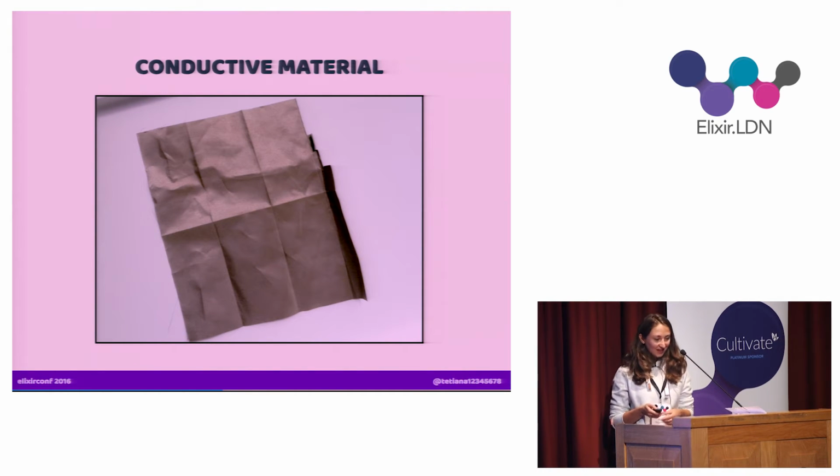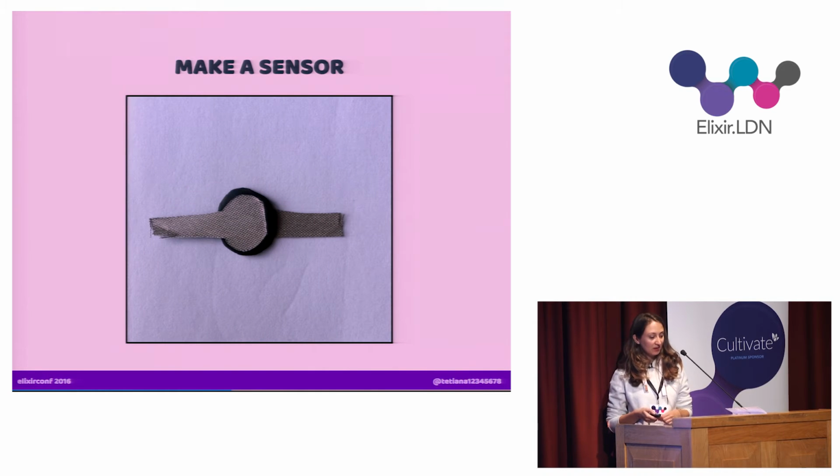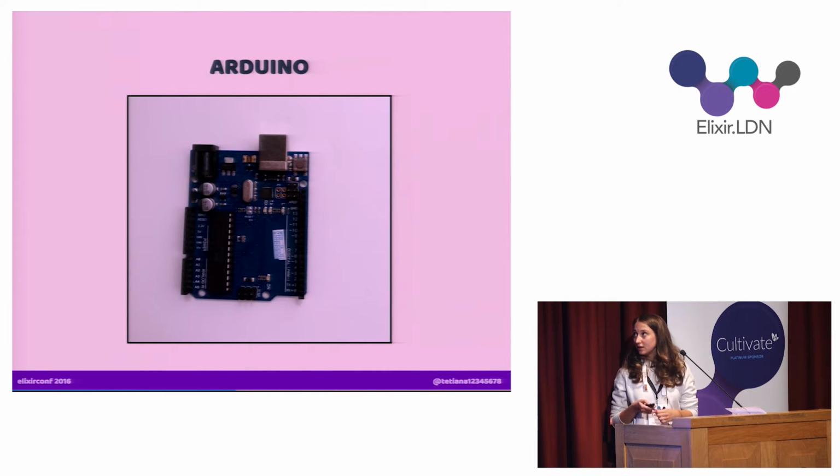So to build the sensor, you have to put this velostat, which is the black thing you've seen, between two conductive materials. And you should make sure that the velostat between those two conductive materials is big enough so the conductive materials are not touching each other, because if they do, then you would have a corrupted signal, which you don't want. And you could build it pretty small, so I just put this sensor next to my finger, and it's quite tiny.